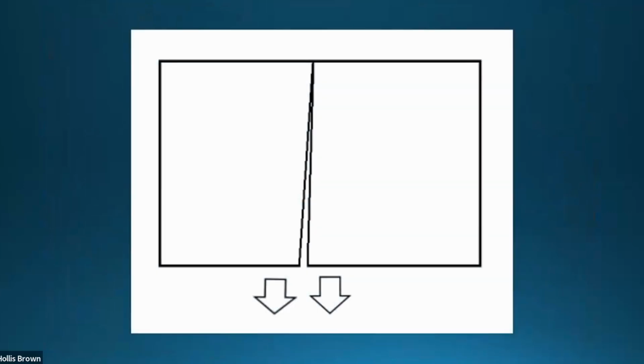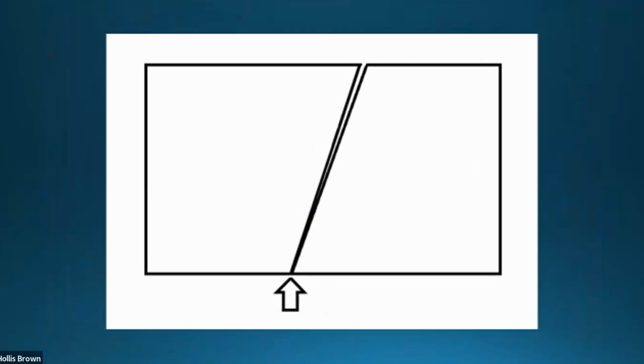So just in general, when you look at cracks in foundations, whether it be concrete or block work, usually if it's a crack like this, where it's larger at the bottom than the top, it's either the footing has buckled downward or the bottom of the foundation is getting pushed in a little bit. And same thing here. And if it's at the top, remember your corners, they're not going to move. So the corners are going to stay plumb. It's the wall inside of the corners that either gets pushed in or the footing has done this. It's far less likely that it's done this. It's really more likely that it's doing this.